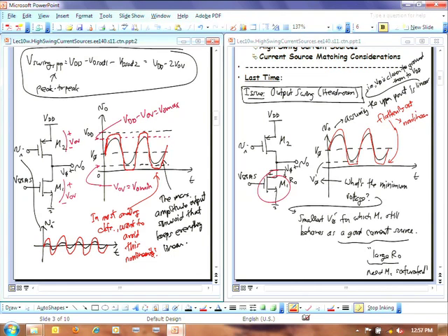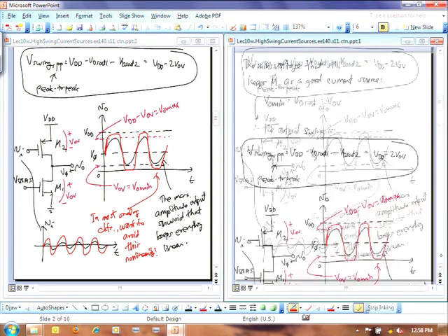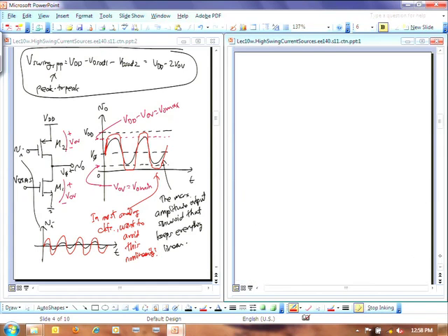Okay? And your cell phones are mainly analog devices because it's much more difficult to convert that EM wave that hits your antenna, amplify that up, then convert that with an A to D converter to digital, then digital is done after that. Okay? So that's what we're worried about. We're worried about being able to handle these analog signals, but why are we worried about the swing? We're worried about the swing because of what's called dynamic range.